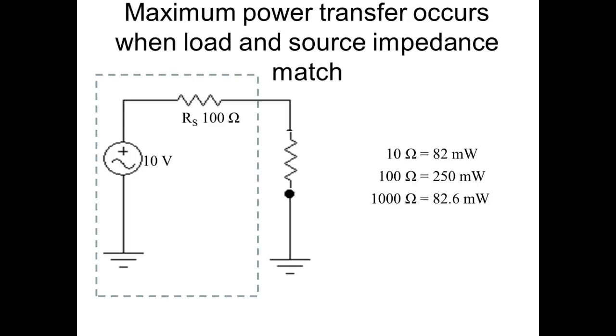We're combining inductors and capacitors with a certain twist per inch and all this kind of stuff to set the impedance of the cable. Now on coax cable, it's the spacing. It's that insulator between the inside conductor and the outside conductor that they call the shield. So that spacing right there sets the capacitance, right? Yeah, that plastic in there, that insulates.